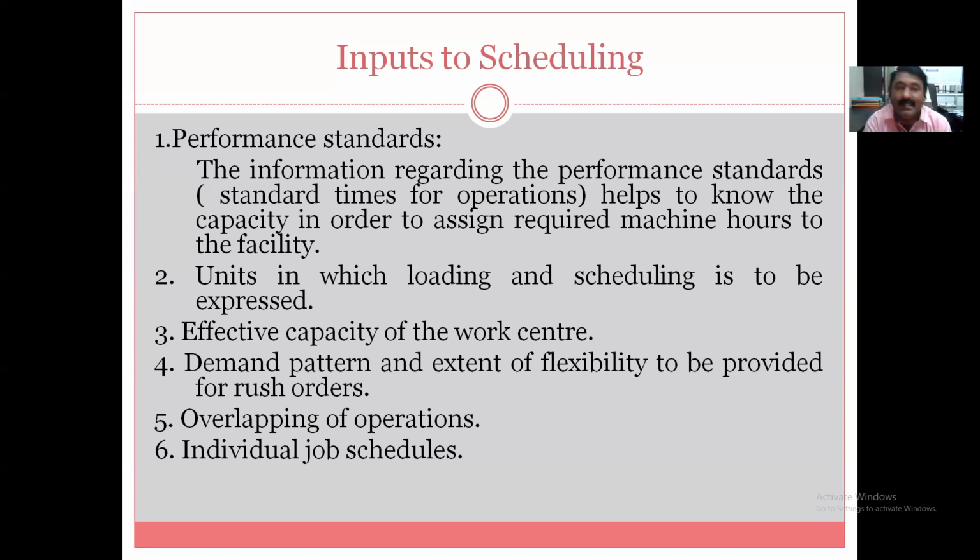So 8 hours, 96. So you can see divided by 8, 12 items per hour, it will be the rate. Again, you divide that 60 minutes by 12, you will come to know that 5 minutes. But it is a continuous operation. No break is considered here. Continuous, the machine is operating. So this may be unit, may be per shift or per hour, per minute.